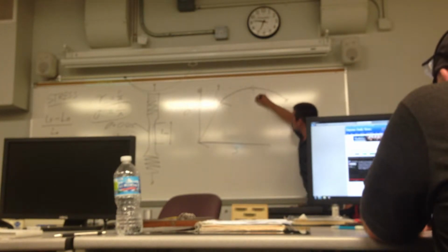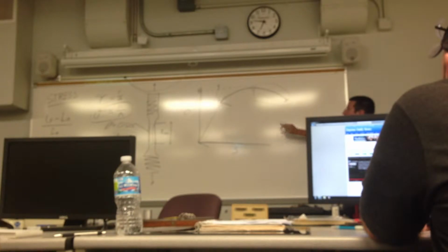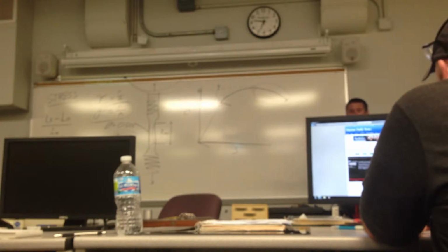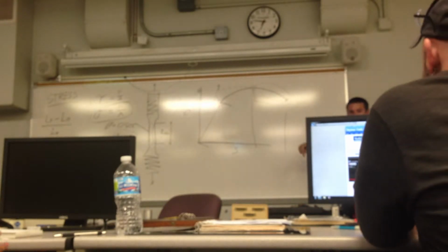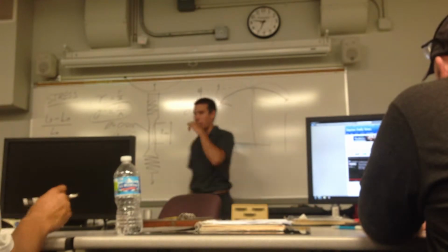After this section here, you have this whole area, and then you have breakage right here. This whole thing is called catastrophic runaway. Once you reach this point, you're getting a huge amount of strain. I mean, look at this. You're moving this much in strain, and you're only reducing stress. So that's the point where it's just pull and break it. There's really no stopping it.